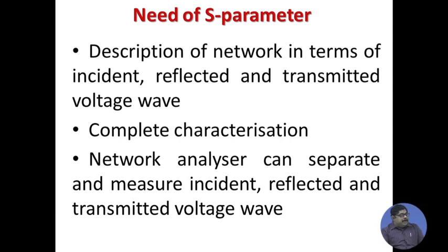separate wave quantities, and that is why there was a need to define a new two port parameter, that is called the scattering parameter. So, this scattering parameter describes the network not in terms of total voltage and current, but in terms of incident, reflected and transmitted voltage waves. That is why it solves the problem of measurement of these voltages at microwave frequency.